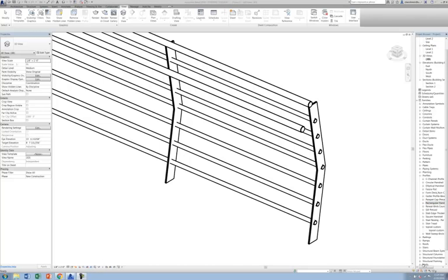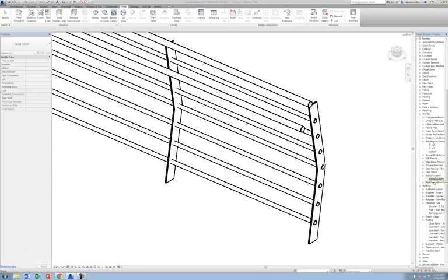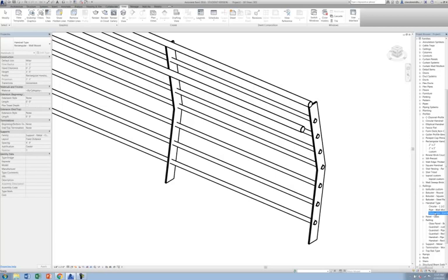Let me look at this. Alright, sorry. So our top rail custom is already loaded in here as a profile. Where we need to get it defined is at the next level, which is at the handrail type. So I've opened up railings and handrail type, and here's where I can select, say, rectangular, duplicate it, and rename it to call it custom top rail.